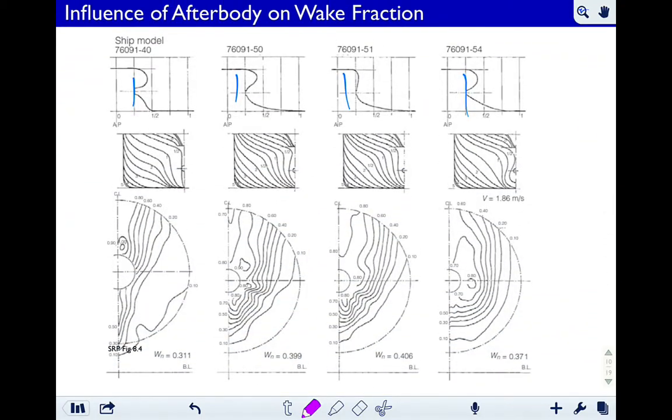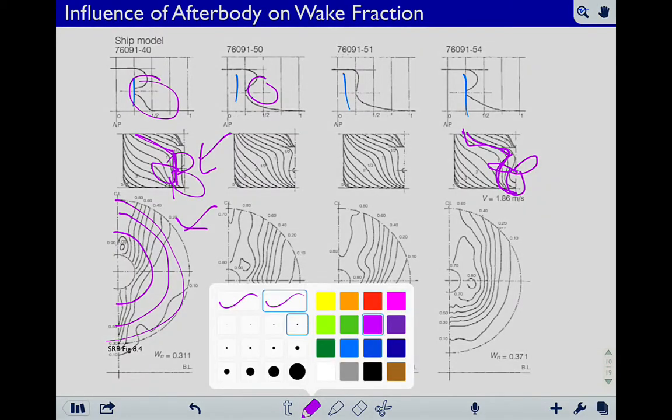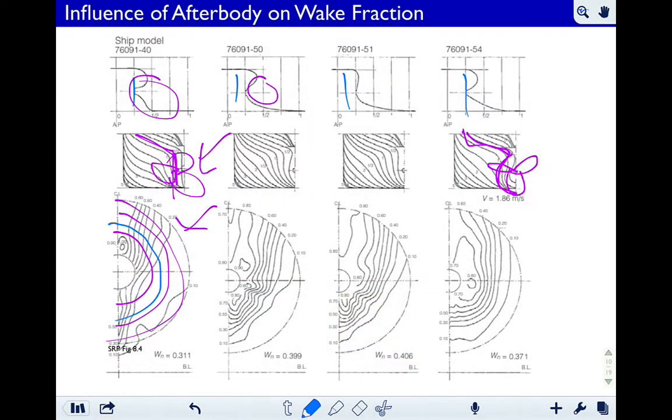We also talked about the afterbody effects, very slight variations in the geometry of the boat. It's easier to see through the section distributions, where you have right at the afterbody a fairly flat section like this, and then the propeller disc goes on like this. And here is an afterbody that has a very rounded, plump stern on which the propeller is attached here. And if we look at these circumferential distributions, ideally our wake fractions would just form closed circumferential loops. So we might have a radial distribution, but along a single circumference, like this blue one here, that section of the blade is experiencing a constant wake fraction, so it's not loading and unloading.